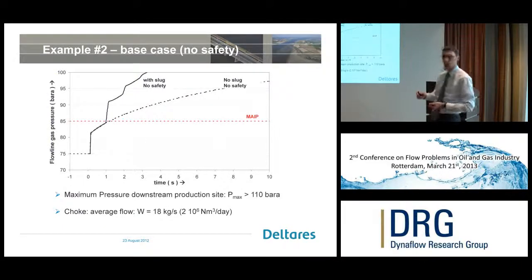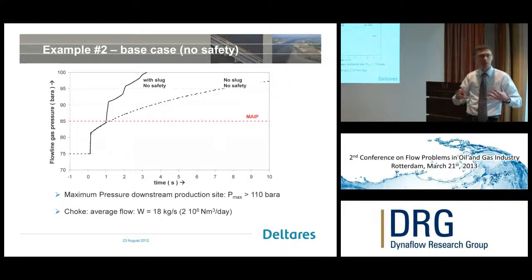But now what happens is totally different. So we see here the black dashed line, that happens without the slug. But if you include the slug, the shock wave of the gas impacts on the slug, but the slug is still not moving, so actually it is acting as just a fixed boundary, a closed valve, you could say. So the shock wave reflects and goes back, and in that way the pressure goes up very quickly. Only after a while the slug gets accelerated, and then you also see that extra volume is created, but that's already far too late.